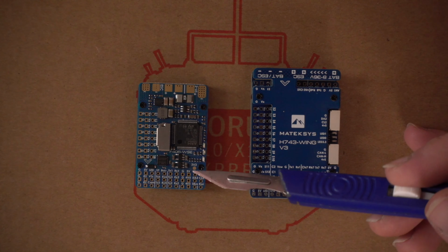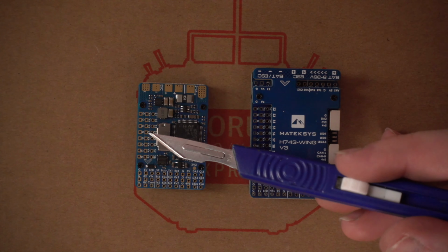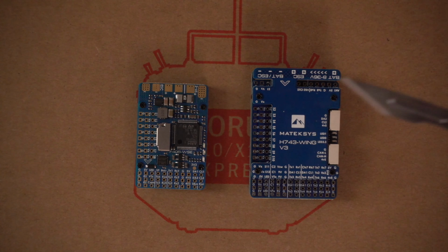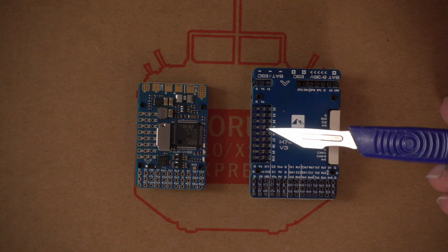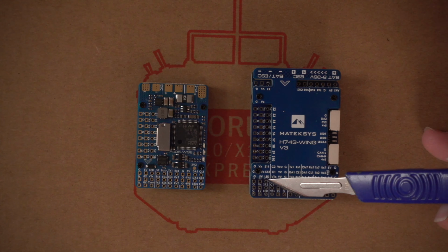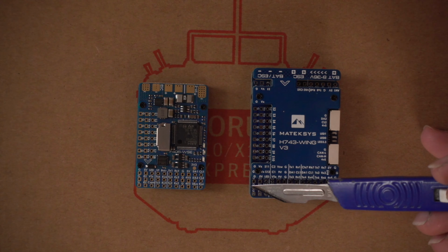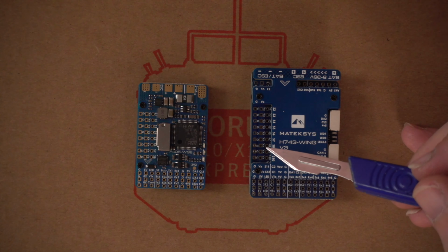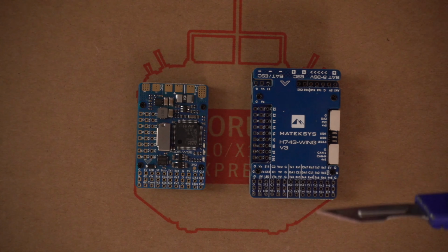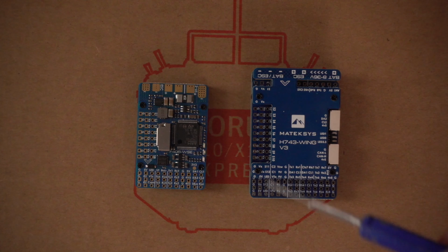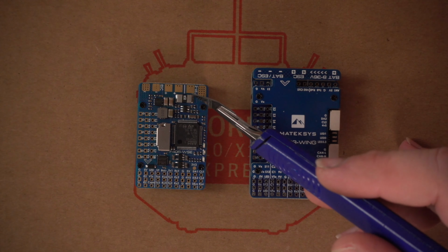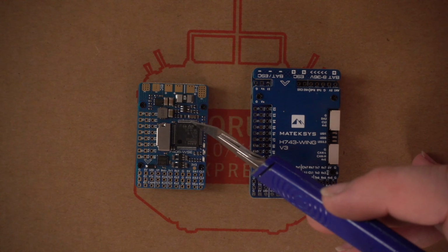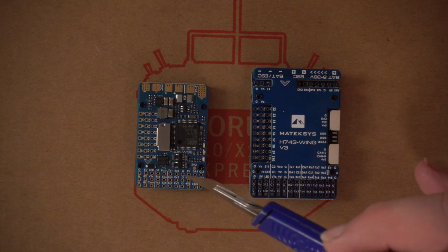So there's going to be a voltage for our servos, which our servos plug in here. Also our motors on this flight controller. And our servos plug in here on this flight controller, and also there are two extra servo pins here. For the servo voltage on these, you can see it says VX, and the X is just signifying a power rail. So a power rail is basically, it will take this voltage from your main battery and step it down to another voltage and distribute that voltage around a rail.